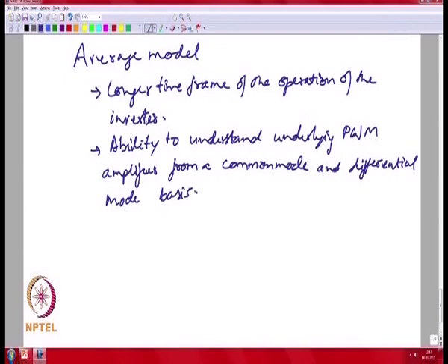For example, you might have a low frequency spectrum of your PWM amplifier. In many advanced PWM modulation methods like space vector, discontinuous modulation, etc., one might consider adding a third harmonic. So, you want to look at the path for the third harmonics in the overall system through the filters, etc. You also have low frequency non-idealities like distortions, deadbands, etc., and you may want to look at the model of your inverter from a low frequency perspective to study these effects more closely.